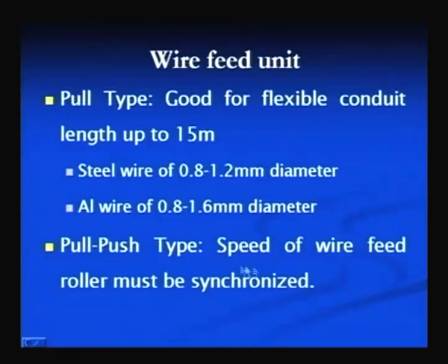If there is any difference in the push and pull type feed systems, then the wire may fracture and the whole exercise may be futile. That is why the speed of the wire feed rollers of both pull and push type should be synchronized.